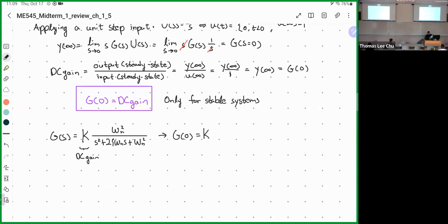For purely oscillating systems like marginally unstable systems, I guess in a sense you can find the gain because the max peaks will be your output, but I wouldn't really worry too much about that. Because it's not staying at a single maximum value, so there is no steady state value, so you can't compute that.